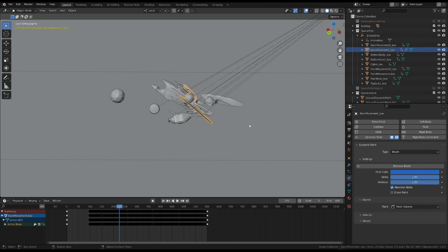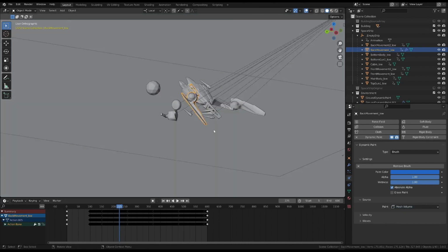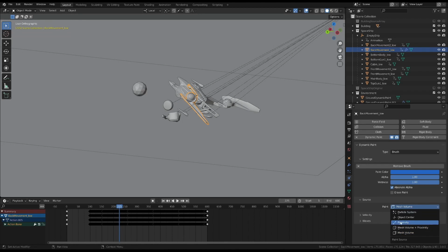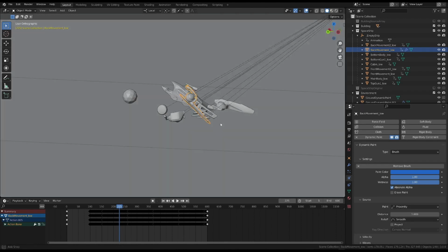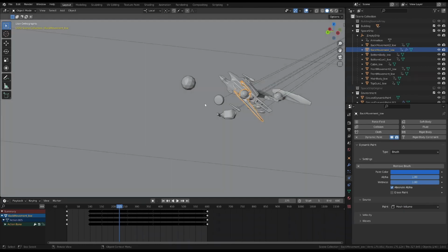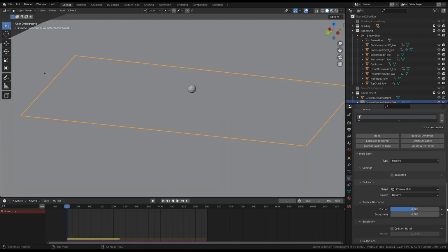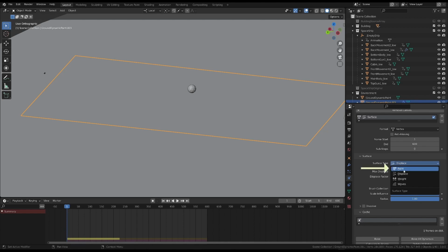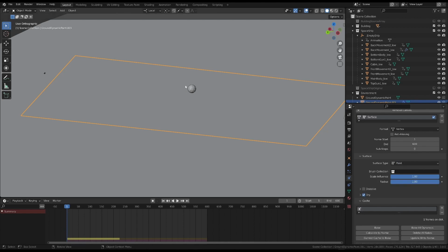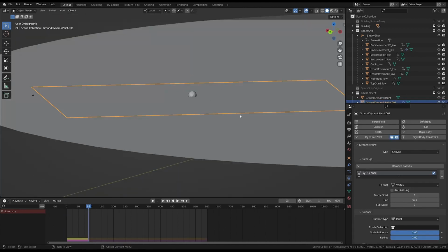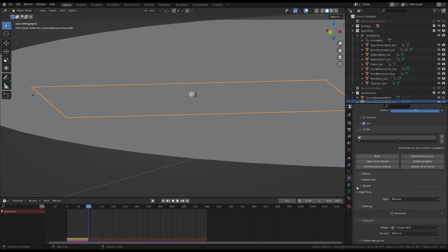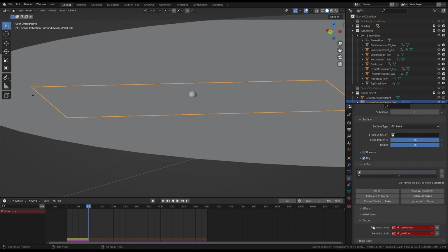The default choice is Mesh. Proximity means that the brush can also paint the canvas from a certain distance away. But this doesn't work in the case of displacement. By adding a new object, like a sphere, and setting the canvas to paint mode, we can see how proximity works. Be aware that paint doesn't refer to materials, but to vertex paint. We can see this if we make a new vertex group in the output section of the canvas. This is the group of vertices that the brush will paint.